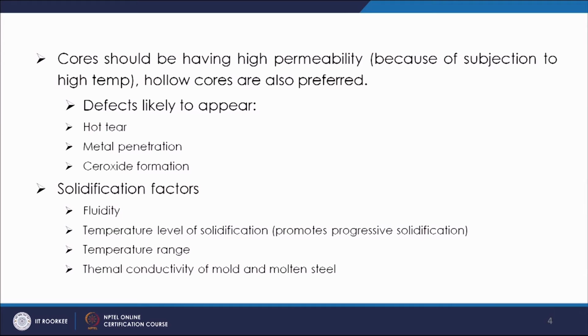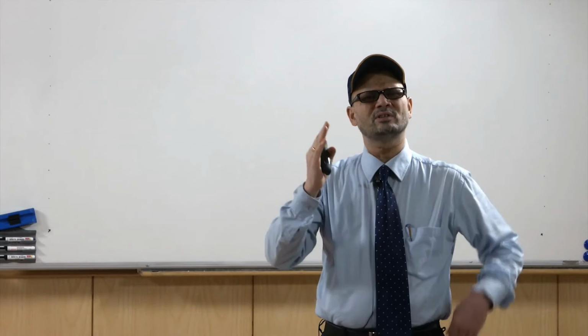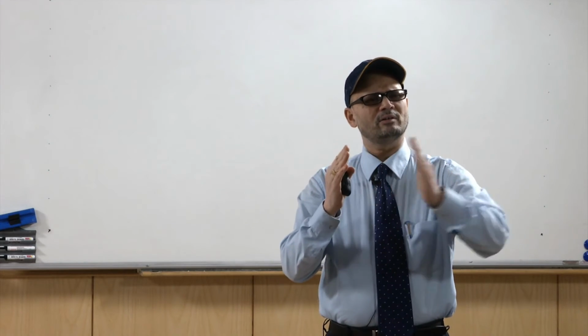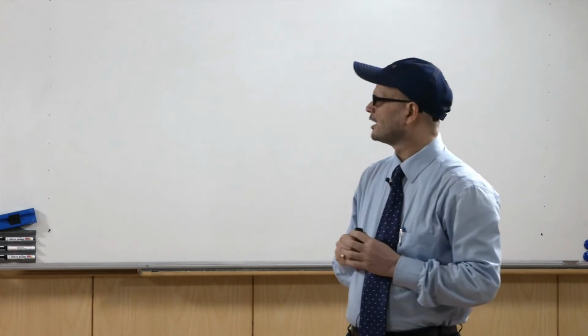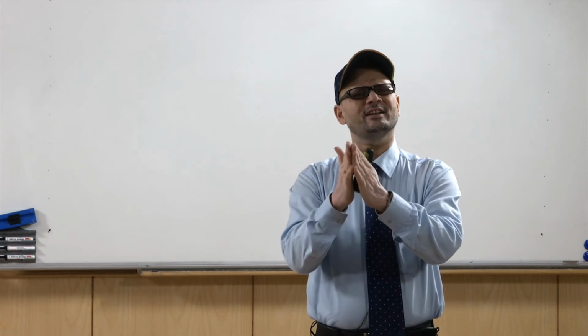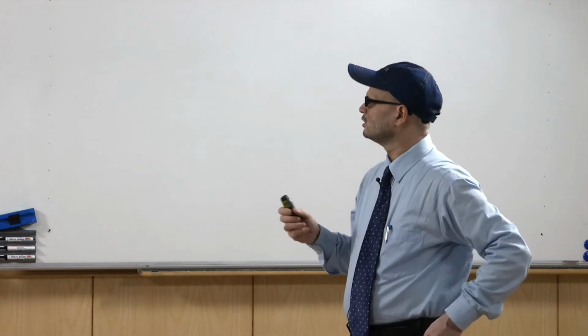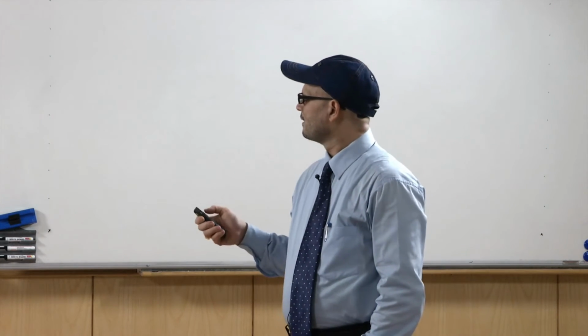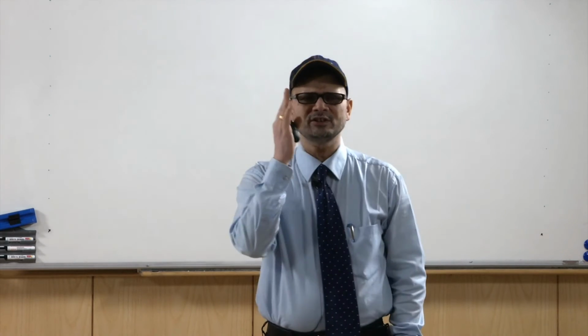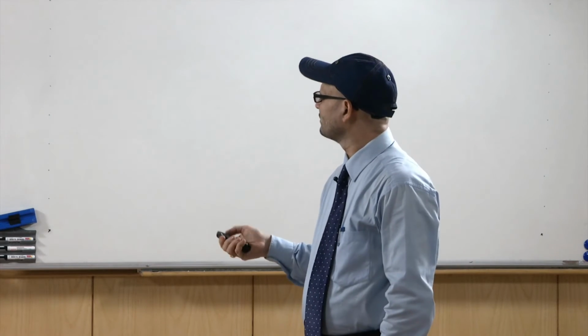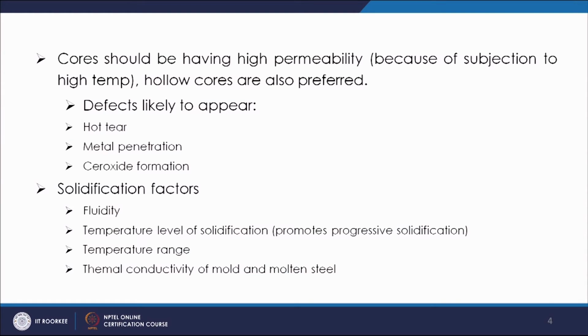When the temperature is higher, the heat has to pass from the interior of the casting towards the mold surface, and then from the mold surface into the atmosphere. Being higher in temperature in the interior part, progressive solidification is promoted. That is the advantage, that this progressive solidification mechanism is automatically set.